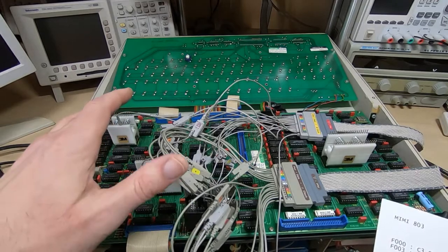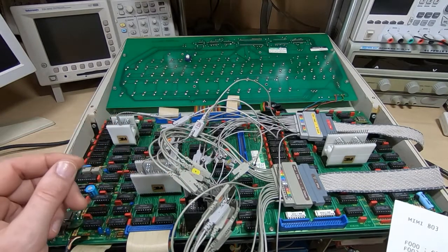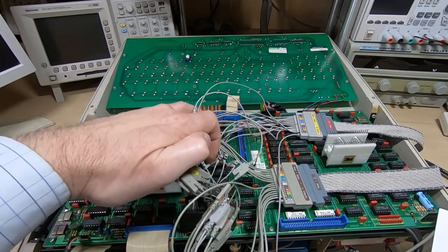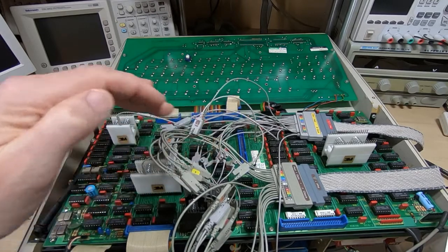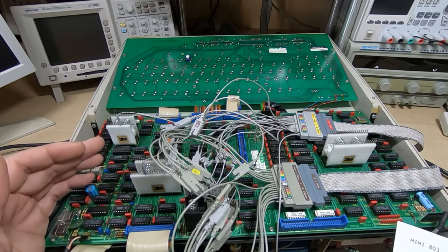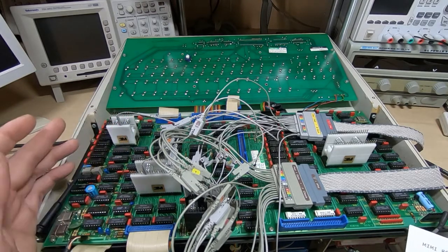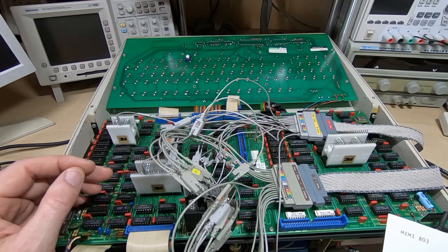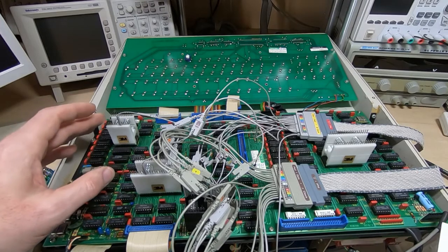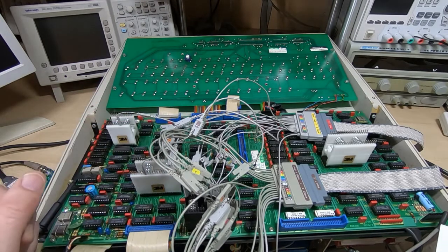So the way it normally works is there's something like a latch or a flip-flop. I believe in this case there's a PROM down here, so I think that may well be involved in some memory mapping. But normally the way it works is at reset there's a flip-flop or something similar, and it's used to map the ROM into apparent zero address space.